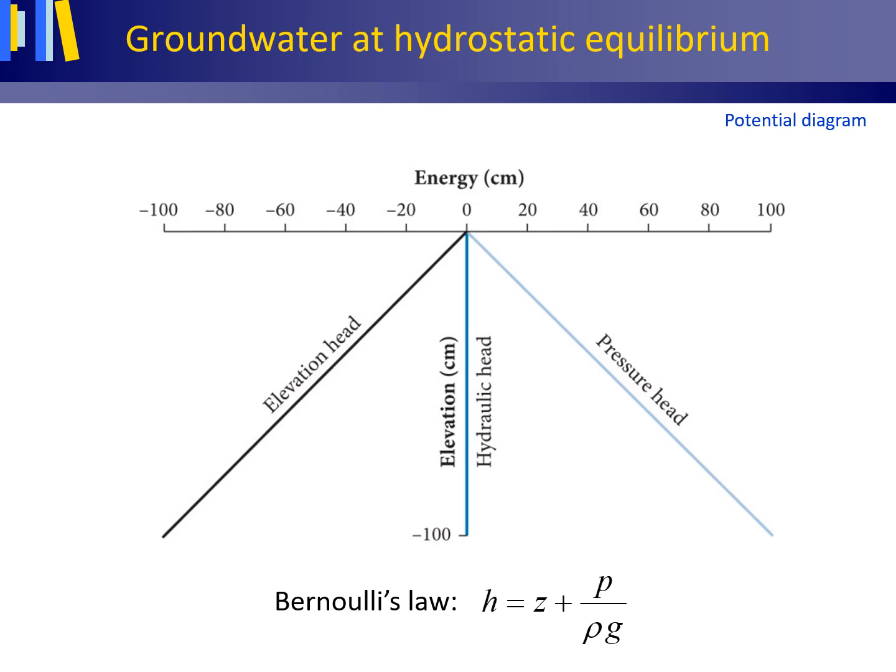In this figure, the elevation of the groundwater in length units is given along the vertical axis. The energy levels of the hydraulic head, elevation head, and pressure head, also in length units, are given along the horizontal axis. The horizontal axis thus has a double meaning. It gives the energy levels, and the axis is positioned at the level of the water table.